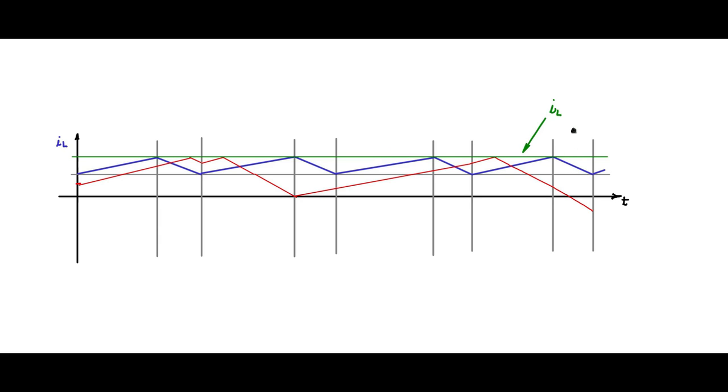So that is IL ref. Whenever the inductor current reaches IL ref and tries to cross that, then the error changes direction, becomes negative, and then resets the flip-flop. But that is not happening in a proper way when the duty cycle is greater than 0.5. Now let us try to change the shape of this IL reference line. Instead of being a straight flat line, let us introduce some slope.